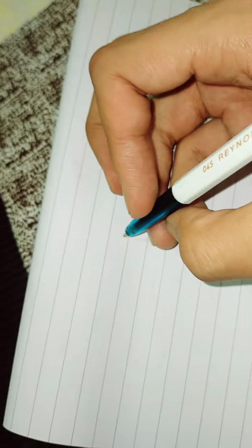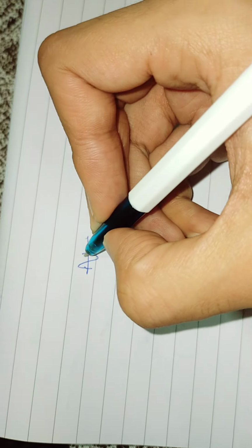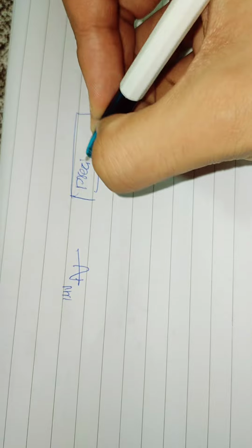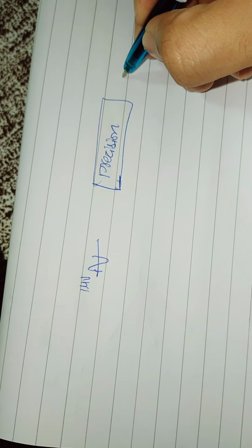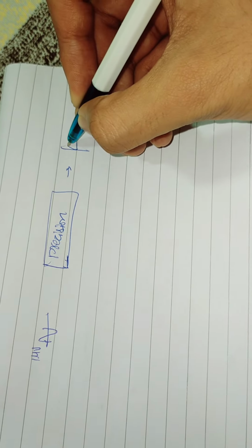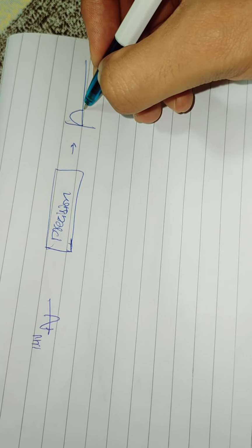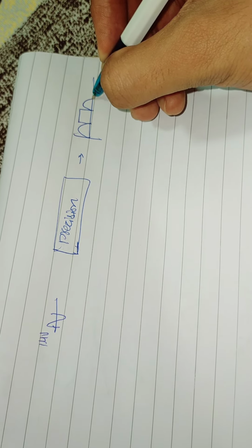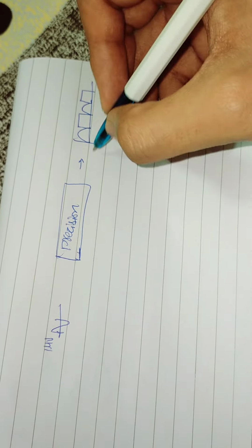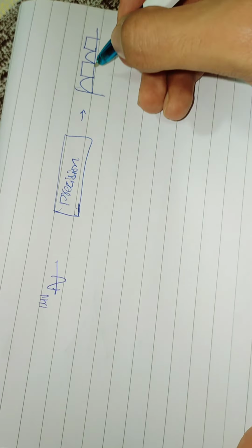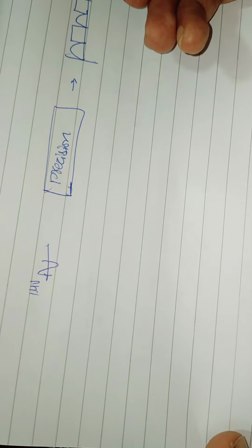There was one question from analog electronics, in that they asked that you have to build a rectifier circuit which is able to rectify a signal of 1 microvolt. So I used a precision rectifier. Then they asked me to make some changes in this precision rectifier so that it is able to provide a waveform like this. In the first half, it should give me the same as input. In the second, it is giving me a square. Then again this, then again square. So it is based on a combination of precision rectifier as well as an op amp in open loop, or a Schmitt trigger you can say, and then we have to add the waveforms. So there was a waveform manipulation question like this.